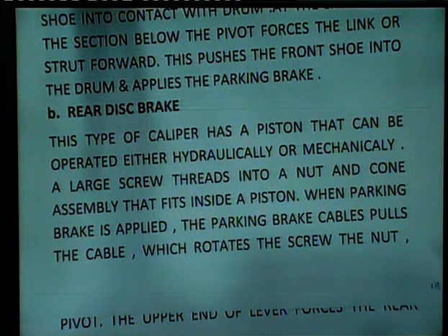We can apply the parking brakes in both ways, hydraulically as well as mechanically. If the vehicle is light, we can use the brake mechanically, or if the vehicle is heavy, the hydraulic brake has to be applied. In the hydraulic brake, there is a non-return valve which is incorporated in the flow system of the brake system.